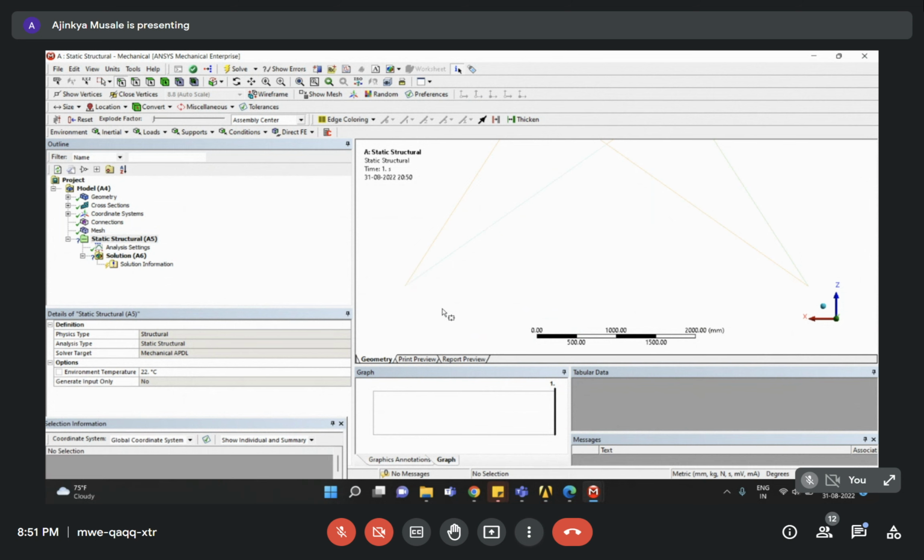And if I'm going from right bottom to left top, so currently I am into the vertex selection only. That's why it is selecting vertex. If I go into the line selection and then perform the same thing, it will select whatever is coming. Even if I'm selecting a small portion, it will select the whole part of my body. So that's the difference between the two-way selections.